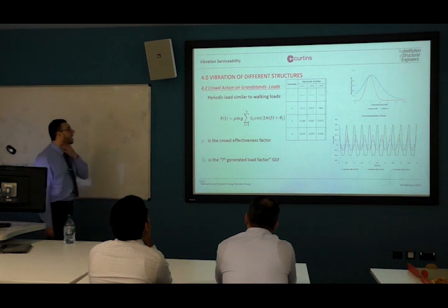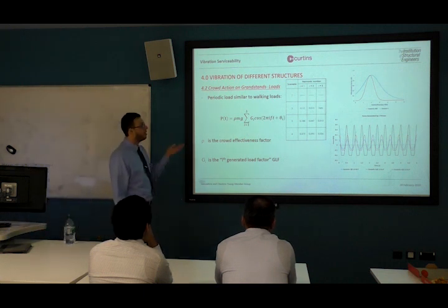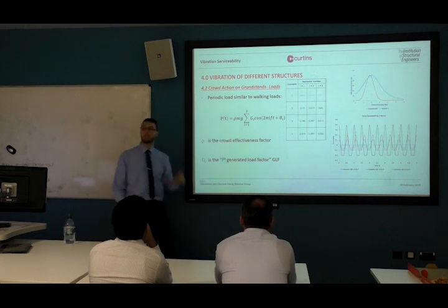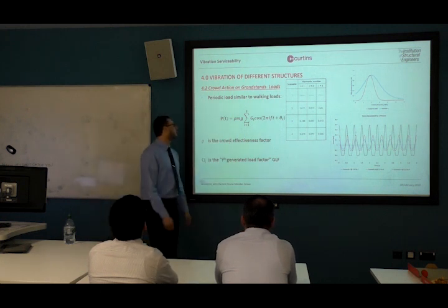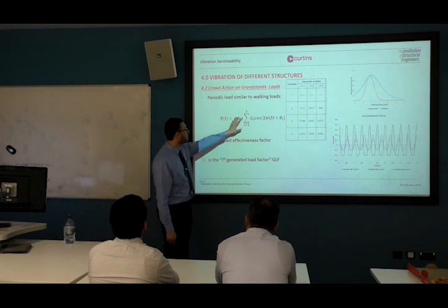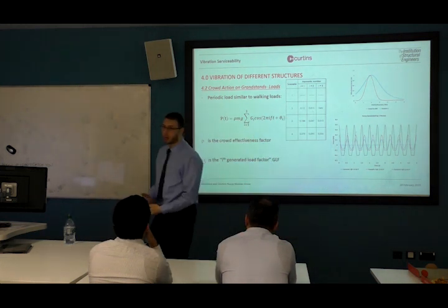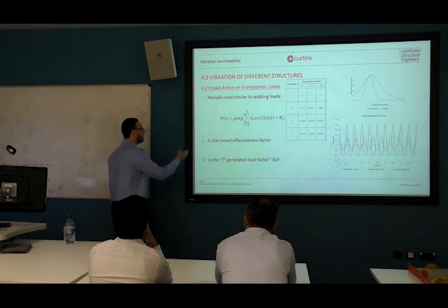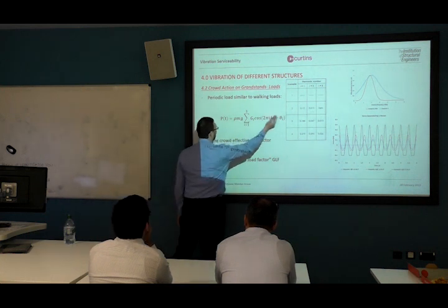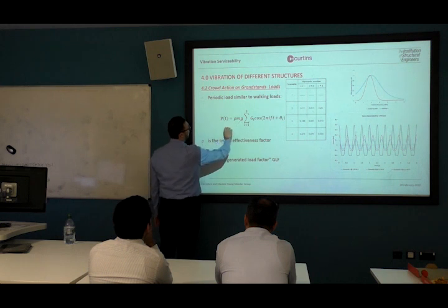Right, so how do we apply the loads for these scenarios on a grandstand? It's very similar to walking actually. It's a periodic load. So we have this equation, which is a sum of sinusoidal loads, again because we are talking periodic, but these sinusoidal loads are multiplied by a factor rho mg.